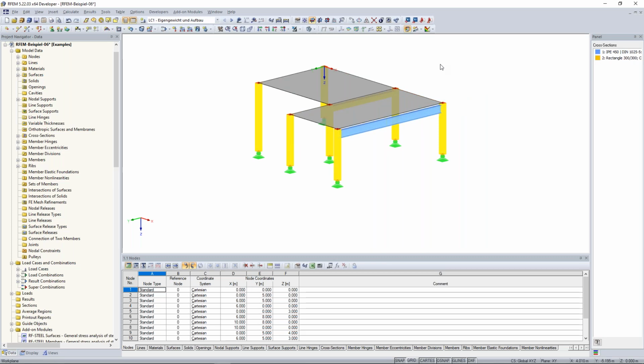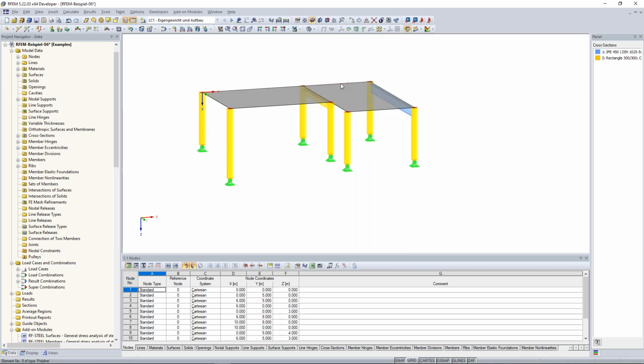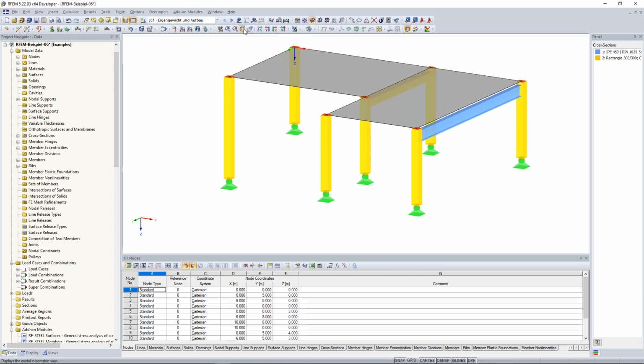Of course, you have the possibility to modify your symbol bar just with the right click here and say customize, and then you can add or delete some symbols and so on. Also with the views, you can change something. So if you like this view and you want to change to the normal isometric view, just click here and the program is shown like that.